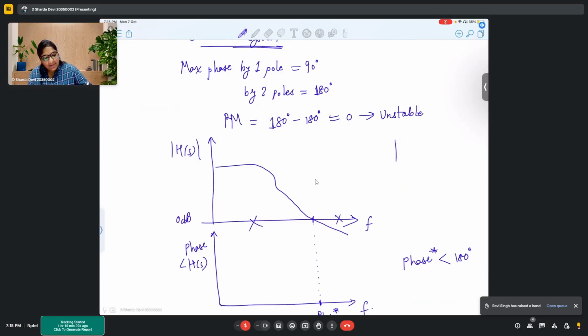If my transfer function for my system is somewhat like this, I want the maximum region I could get to be of a flat gain so that it does not introduce any distortions. So this is my bandwidth, right? And this is because of the pole that we introduced. So I want the highest possible bandwidth that can be obtained.